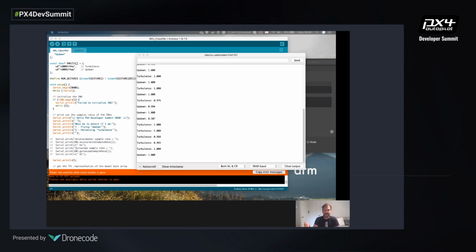Don't forget that the i.MX8, for example, has multiple CPUs. Some of them will run Linux and will run containers, and will give you the ability to run machine learning in a different way. And then there are also Cortex-Ms on there, so you could potentially run TinyML on those Cortex-Ms.